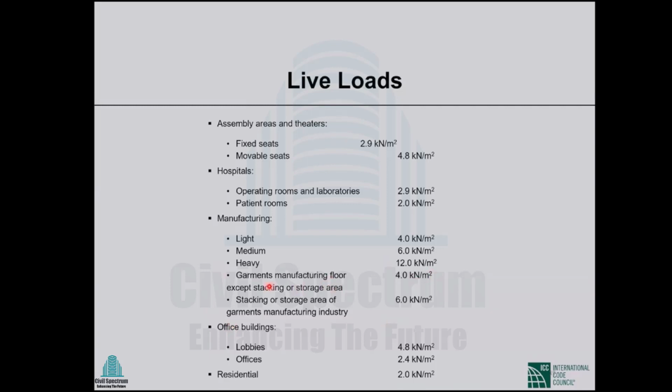One is for common floors, without the storage area. The recommended live load is 4 kilopascal, 4 kilonewton per meter square, which is equivalent to 80 PSF. And for storage areas, this is 6 kilopascal, kilonewton per meter square, which is equivalent to 120 PSF.